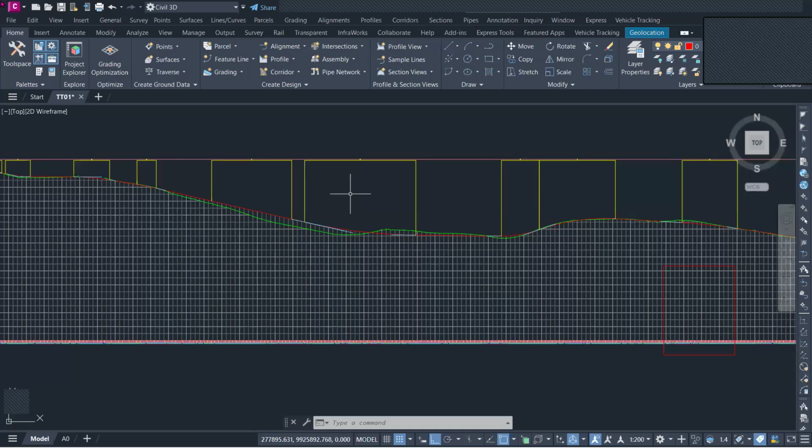It depends on the production specifications. So if you're measuring your culvert internally, then this means this will be 900. And then there is another 200 here. And then there will be another 200 on top, okay? Or 150, it depends again with the specifications. Some have 150, the ring is 150. Others, I think mostly it's 150, not 200.